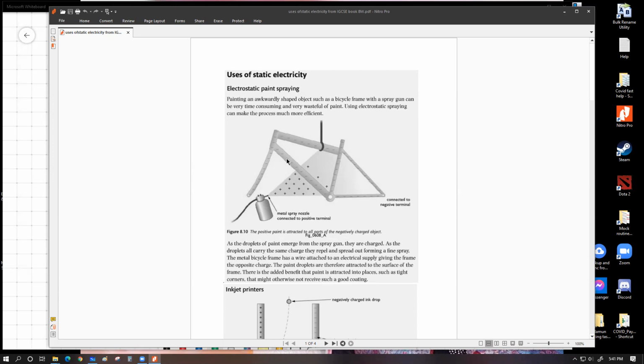So that helps with less wastage and a much faster painting process, and also ensures a pretty uniform thickness. Because if you are not doing electrostatic spray painting, only the front hemispherical region or only the front cylindrical part would be painted. Nothing behind the surface would be painted. To make sure of that, you would have to paint it on the other side once again. And where the joint would happen, you would have a bit less thickness of paint.